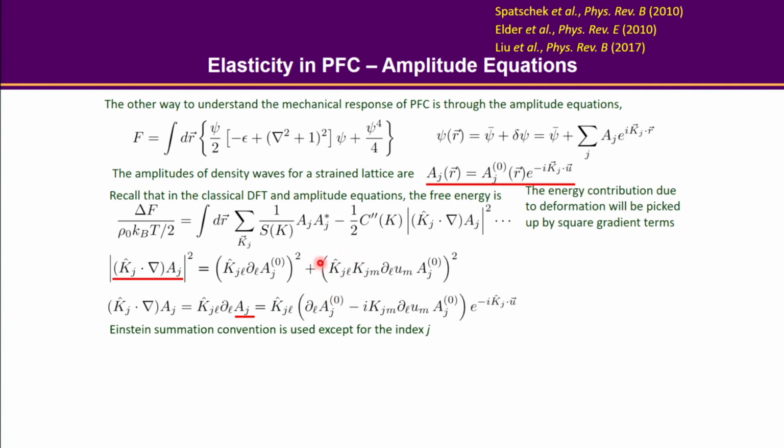So whenever you see a hat, that's a unit factor, you don't see just the factor itself. Okay. Let's digest the result a little bit. If U field is the displacement field, the way we define the strain tensor is just saying how the displacement is going to change over space. So the strain tensor is defined as this kind of symmetric operation. You have a displacement in a certain direction, take a derivative with the other direction, and symmetrize that.